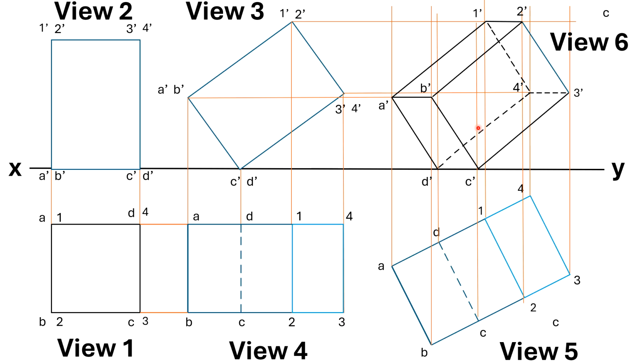The only thing is we need to start with view 1. So where to start with view 1? We need to see and properly start with view 1. If you make a mistake with view 1, with the wrong plane, automatically all the remaining things will be wrong. So you need to start with the correct view 1 in the correct place, whether it is below the xy line or above the xy line.